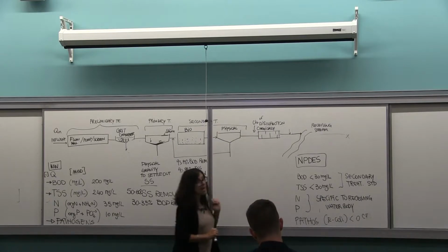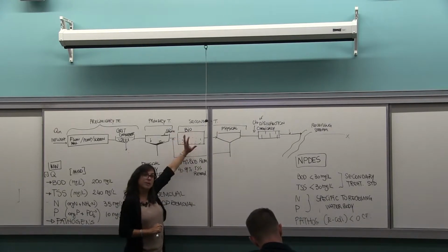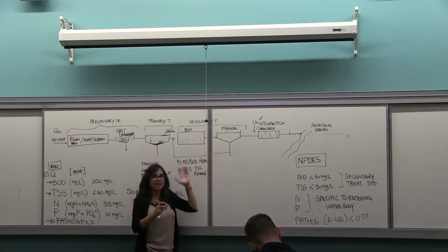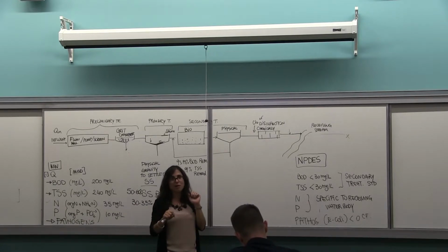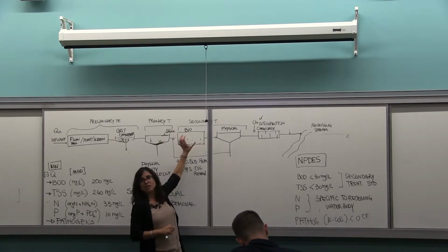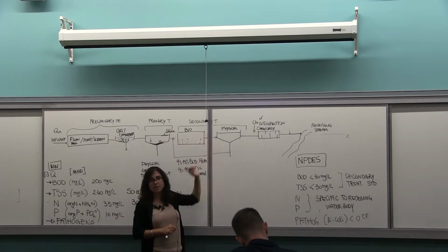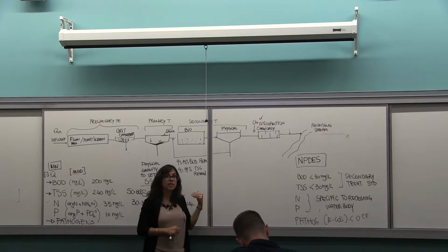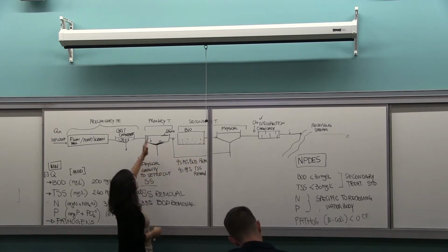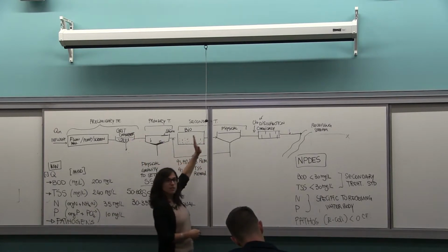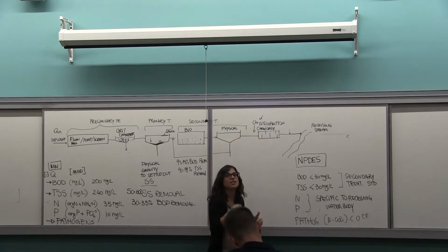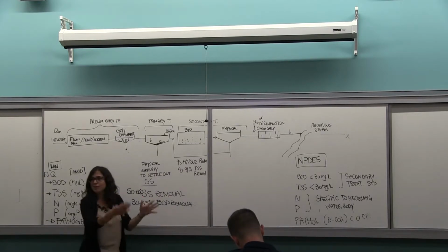Nitrogen and phosphorus are mainly removed biologically. Nitrogen is mainly removed in the biological unit by making modifications, and we'll talk a little bit about it in one of the problems. Phosphorus can be removed biologically, again changing the configuration of the bioreactor, or can be done chemically with addition of a coagulant, ferric or alum, and usually the addition can be done before the primary treatment, or if it's very advanced, you will do it after as a tertiary process with filter and chemical addition.